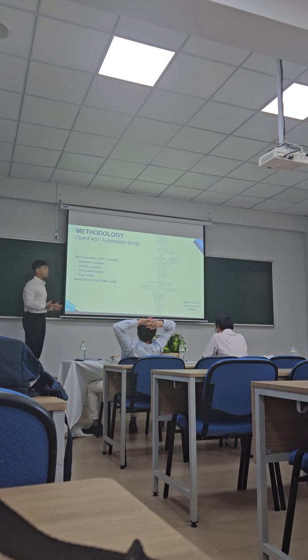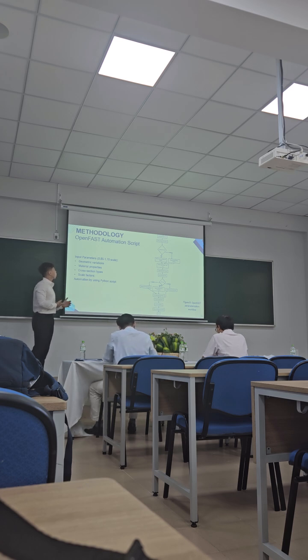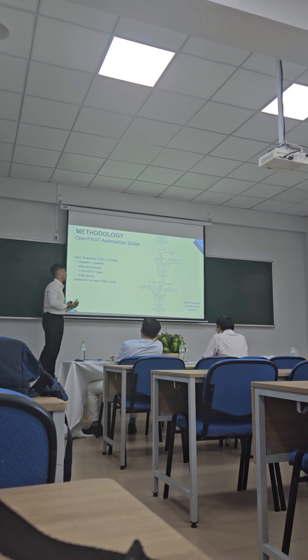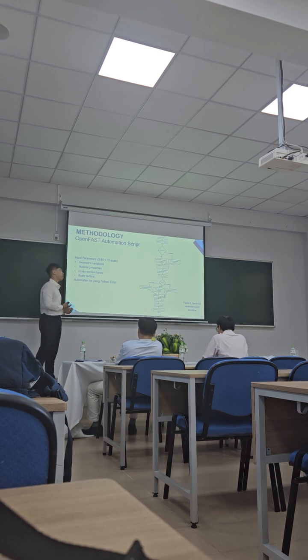To handle multiple cases of the configuration, we have developed a Python script to execute OpenFAST automatically. As you can see in figure 8, the script will define the modified dimensions, including the main column radius, and it will modify the parameters necessary to run FAST. For example, new mass and inertia, the plus adjustment if the material and geometry change, the connecting members' coordinates in HydroDyn, and the fairlead coordinates in MoorDyn, and it will run MoorDyn and FAST. This script enables us to handle all the parameters programmatically and minimize human error.